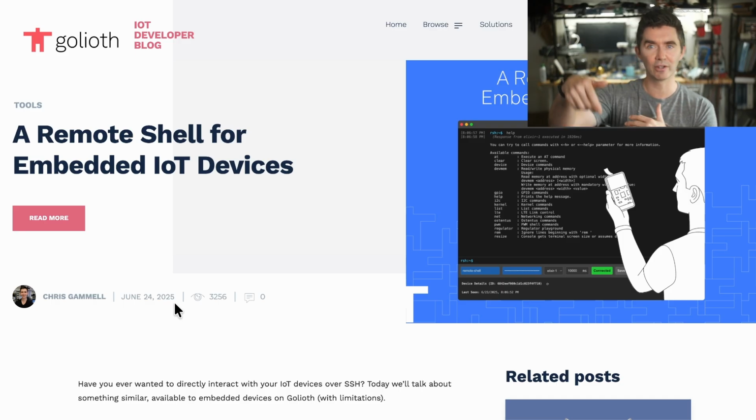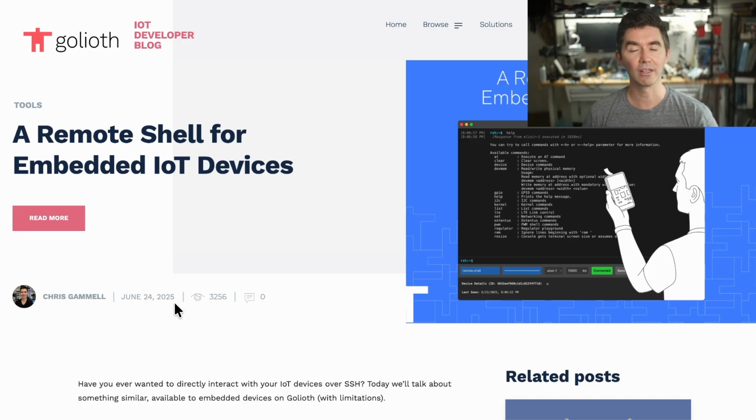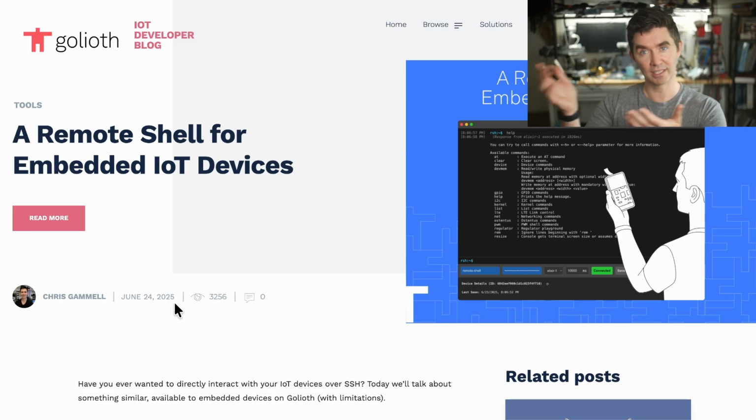That actually talked over the internet to cellular devices, really any Goliath device, and then it could send the data back up using a custom backend in Zephyr. We really like the shell capability in Zephyr and the ability, in this case, to talk to it remotely. But what if we wanted to do it locally? Well, that actually is possible already. It's possible because you're just plugging in over serial or USB CDC. You're talking to the device over its shell.